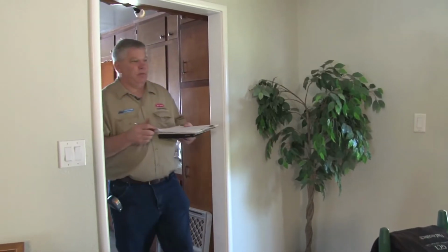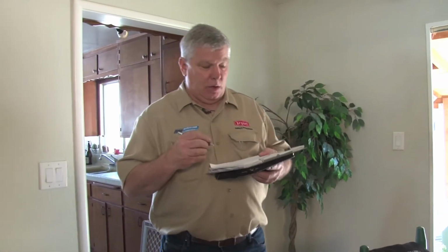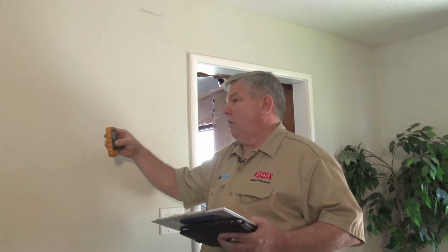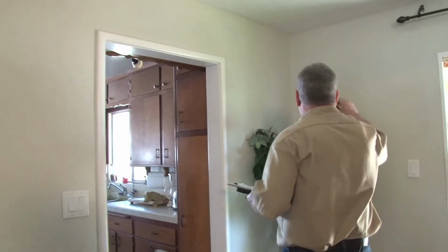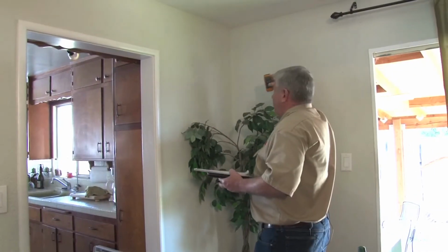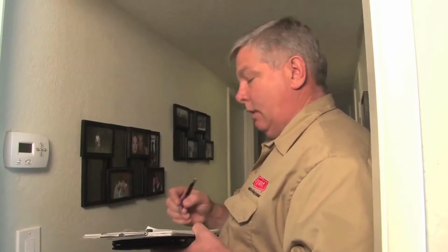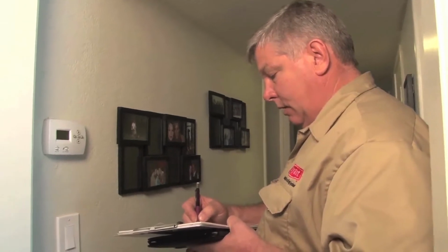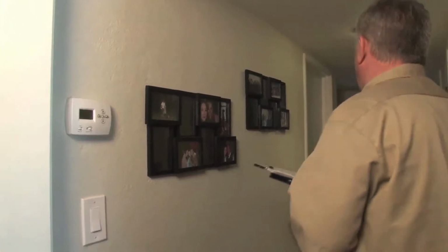Okay, as we continue to make our drawing of the footprint of the home, we're going to keep measuring rooms as we go along. We're going to stop and measure a window here in a second. We'll measure each window as we go through the house, but while I'm here, let me get the measurement of this room. We have 15 by 25. So as we enter the hall, I see the thermostats here on the left, so I'm going to make a note of that as I draw out my footprint, and I have that location.